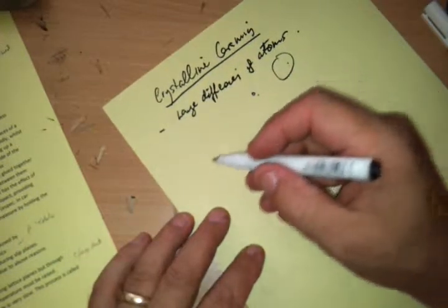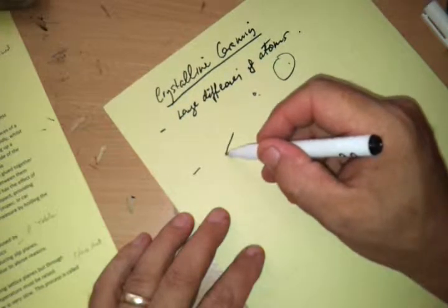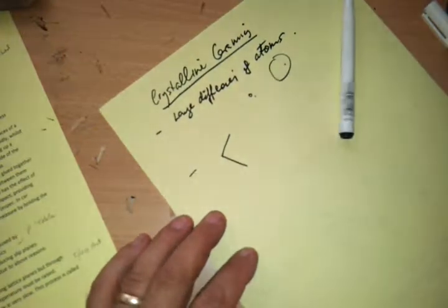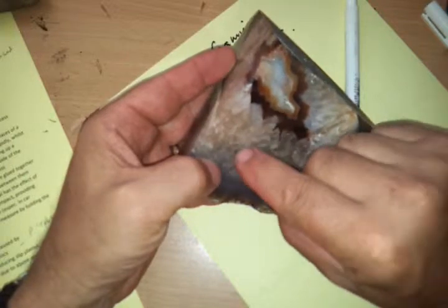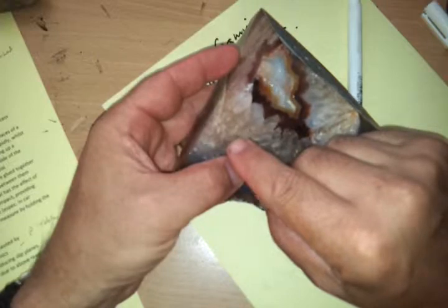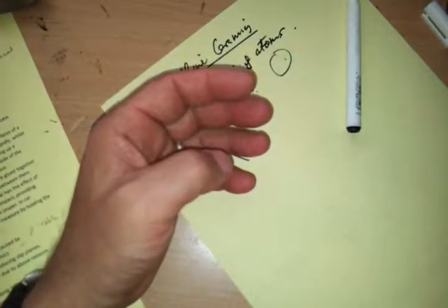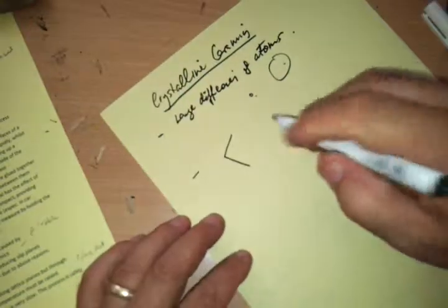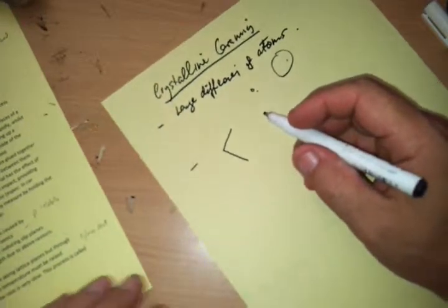The other reason is that there's not much symmetry in ceramic crystals. For example, there's that rock that I showed you over here, and you can see the crystalline structure. It's not an even repeated crystallinity, which means there's not many possibilities for slip planes to slide. So it's not homogeneous crystallinity like in a metal structure. It's different crystals at different angles, and slip planes are greatly reduced. So you're not going to get a nice clean cut like you would on a metal using a ceramic.